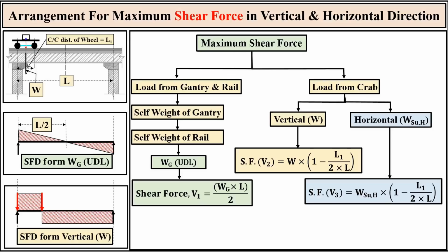The shape of the shear force diagram for the horizontal load is similar to the vertical load. However, it is important to note that the value of maximum horizontal shear force will be significantly less than the maximum shear force caused by the vertical load.